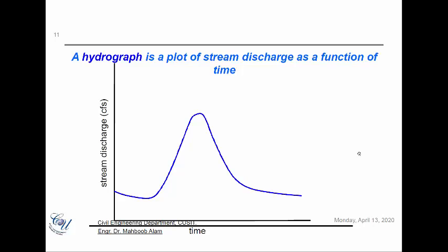So discharge data is usually called the pulse of a catchment, and this discharge is usually shown as a hydrograph. Hydrograph is just the stream discharge in any units versus the time. Time is on the x-axis and the discharge is on the y-axis, and there is a typical shape of a hydrograph, and we will be looking at these different parts. So you see the line here is a little bit decreasing before there is a kind of storm here, and then there is an increasing limb, a decreasing limb, and then returning to the normal situation.